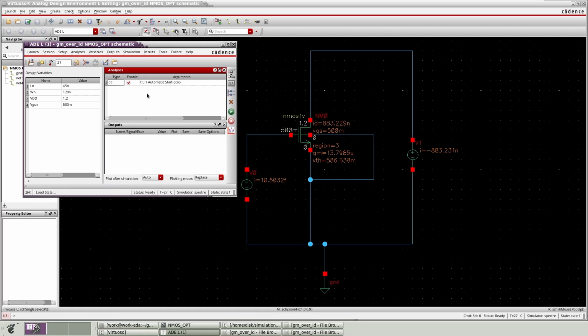This is another type of method which you can follow. Then you will get a combined set of data. Those data are your DC operating points data, and they are very advanced data. So let us see how to add the SCS file. If you have no SCS file, then you cannot see any combined set of data for this NMOS.